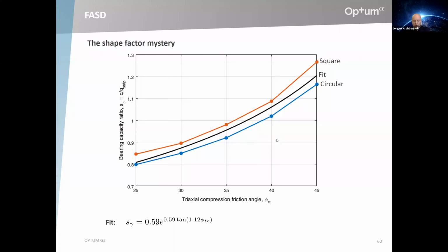Say, Christian, as an engineer, you got a triaxial friction angle. How would you convert that? Which factor would you use? Well, it depends. I would go into my local code and see, does it say anything about it? If I'm in Denmark, it does say something about it. If not, then I would say probably 1.1 is as good as anything.